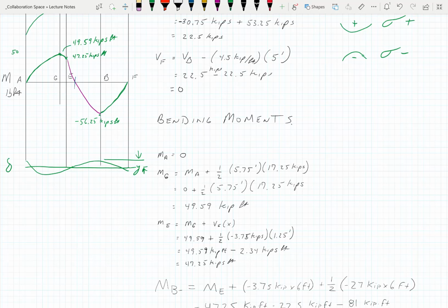So, a little sidetrack here for a minute. Remember I talked about tractor trailers, okay? Flatbed tractor trailers. The old heavy steel ones were always just done like this, and you loaded weight in the middle and they deflected like so, okay? Almost to the point that the front set of wheels in the back got all the weight and the back set got less weight. And if the tire was going to blow, it always blew on the front set. Very rarely just blow on the back set.